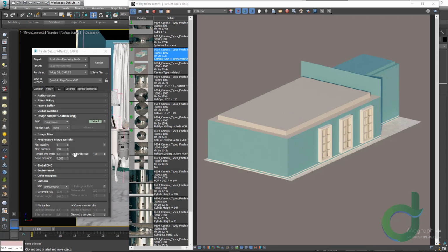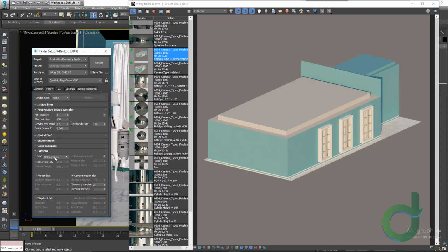Next we have perspective, which overrides the scene camera to force it to be a pinhole camera. We have spherical panorama, which is a spherical camera with independent horizontal and vertical FOV selection that is useful for generating lat long or latitude longitude images for spherical VR use. As you can see, it's like the spherical type, but we get an extra vertical FOV parameter to control field of view vertically. Let's set the vertical field of view to 180 and override field of view to 360.